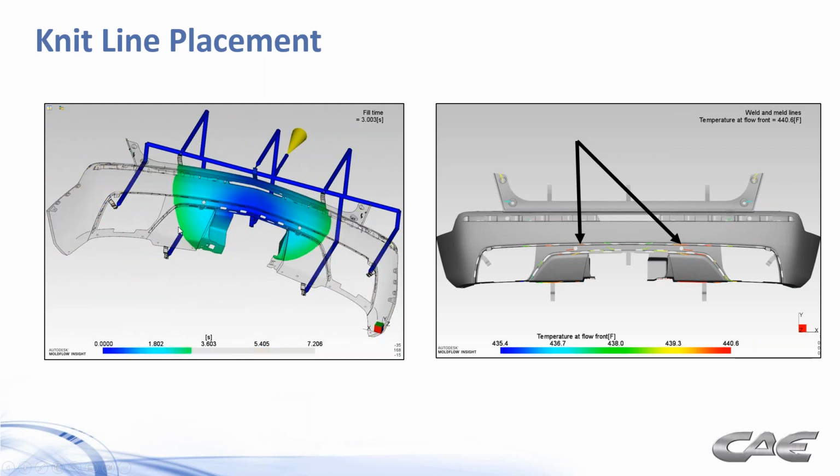Most people are going to fire based on position, the screw position. That's how they set it up at the press typically. It's a little more difficult to calculate that from the mold flow output unless you have the screw and barrel diameter. But even then, there's some initial compression of the material that goes on in the screw and barrel that's not necessarily directly accounted for in mold flow. So use short shot progression studies at the press to make sure that's how you're firing your nozzles. That's the best advice I can give you there.